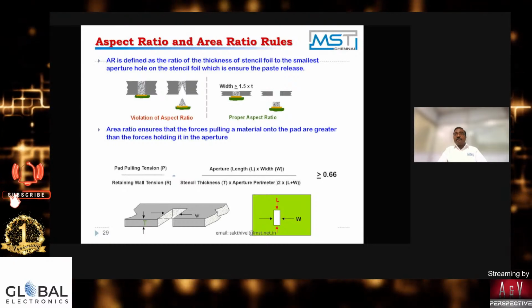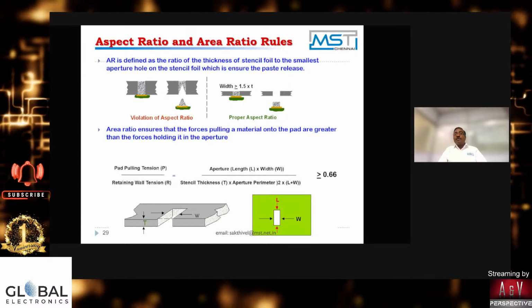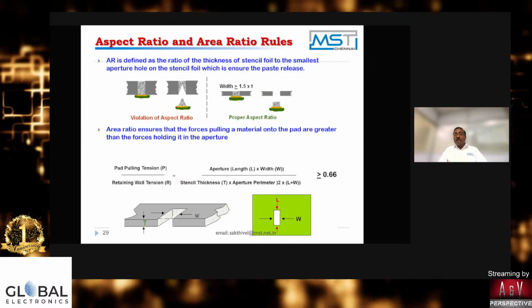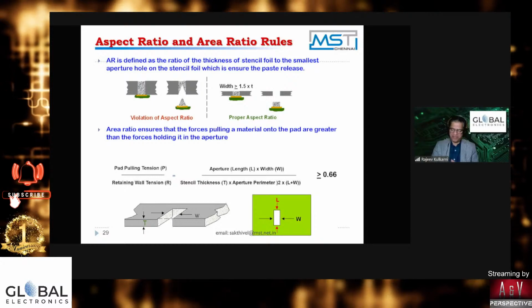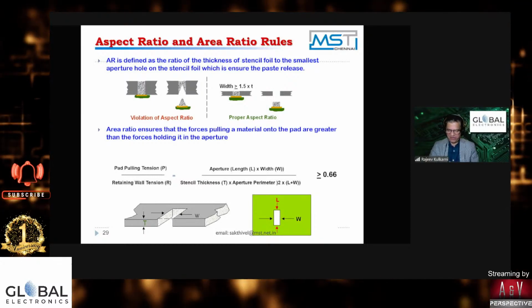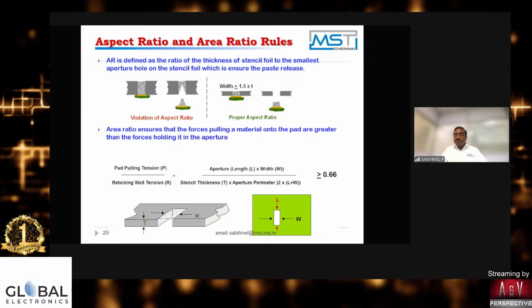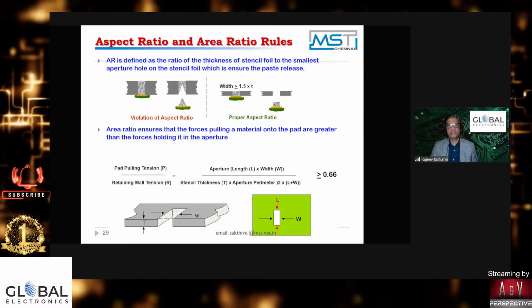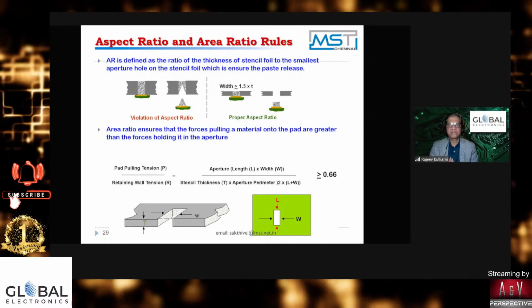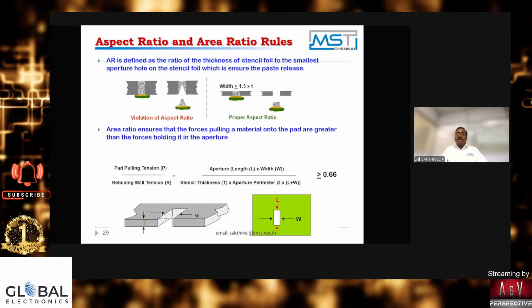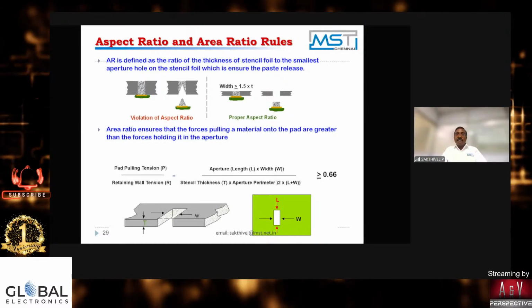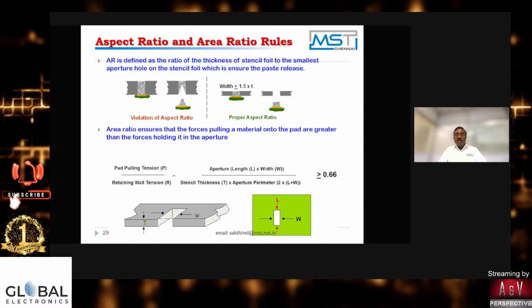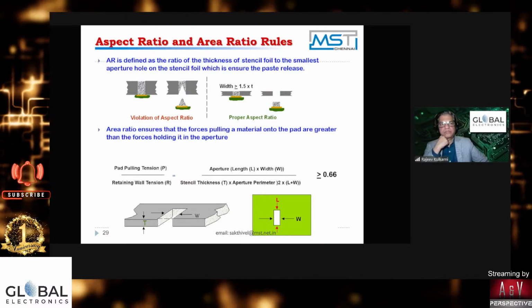The coating thickness is 100 to 200 nanometers. It is not microns, it is nanometers. Is it a surface treatment process you provide as an option, or is it a must? We strongly suggest it to customers who are in the mobile phone industry or high density interconnect, wherever they are using it. For them we specifically say so.